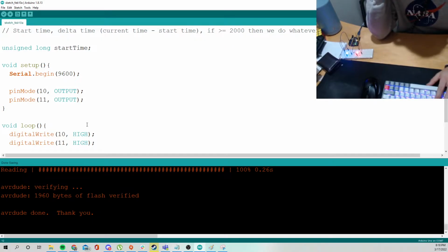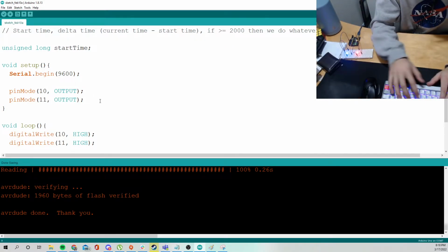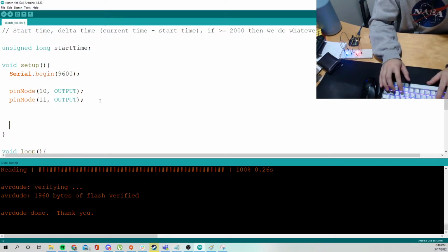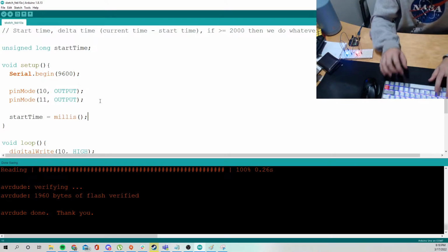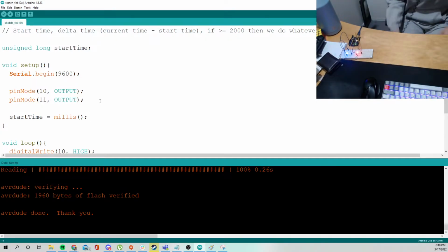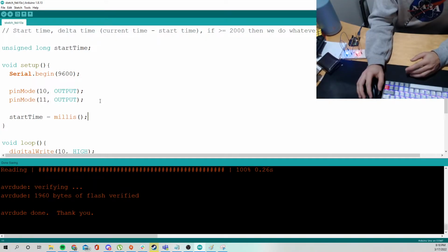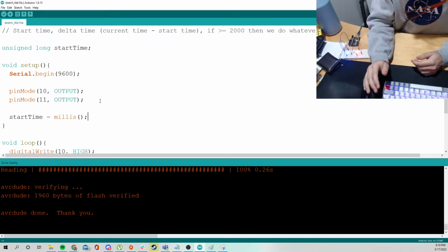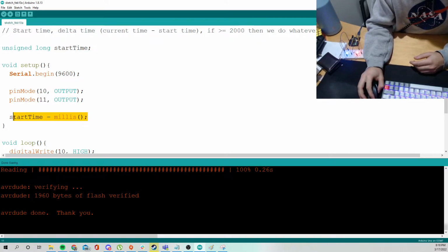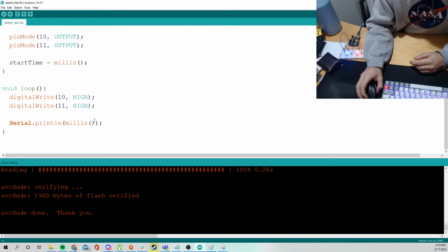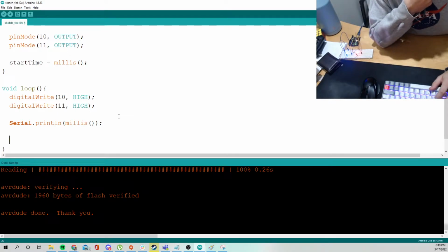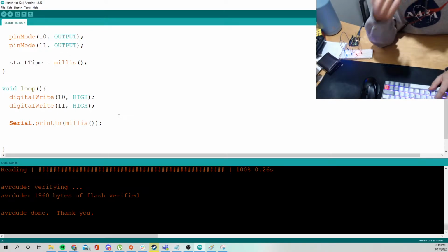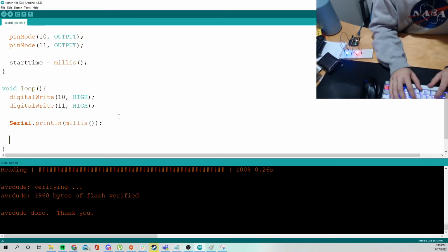So let's go to our loop. Actually, first let's start our timer, right? So at the very end of our function, we're going to call millis, and basically I'm storing the beginning of my timer. At this time, I started calculating or trying to find the delta. Cool. Now I have this. Now when I go to loop, here what I can do is check the current time.